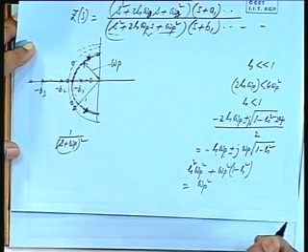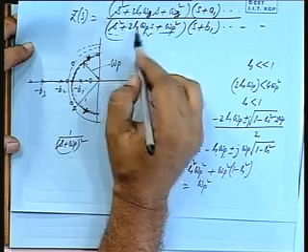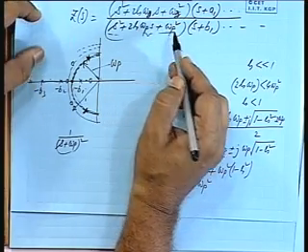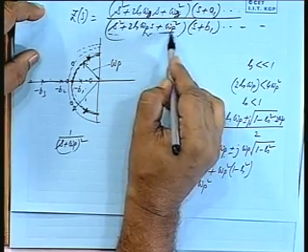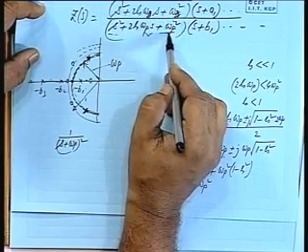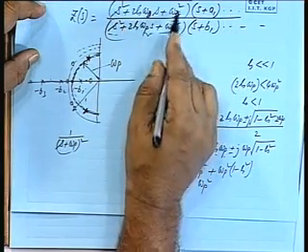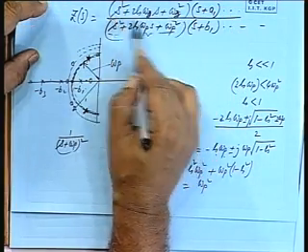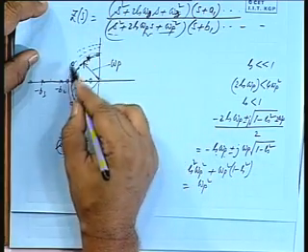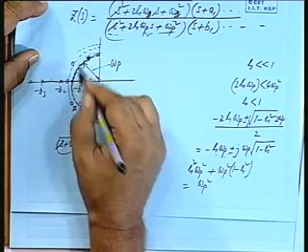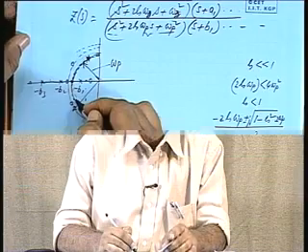Okay. So, depending on the quadratics that will be given to you, the corresponding natural frequencies, you choose the semicircles, and the poles and zeros for that particular quadratic will be lying on that semicircle, and they will be appearing in complex conjugate form.